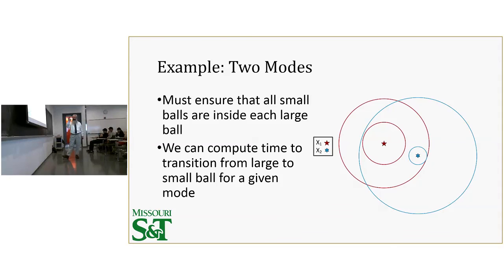All right. So again, our objective here is to analyze a system that can switch among these different operating modes. For each set of inputs, we have some different stable operating point. And so we need to make sure that we wait long enough that we're close enough to that new operating point that we can switch safely.